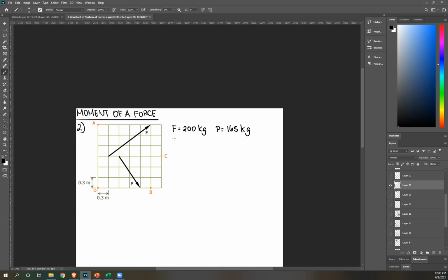Let's start with the force F, so Fx. To get the components, you either need an angle or a slope. Since we're given distances, most likely this is figuring out the slope. So let's take force F. As you can see, it starts at this point and ends at this point, and then it creates a right triangle. From that, we can figure out its slope.